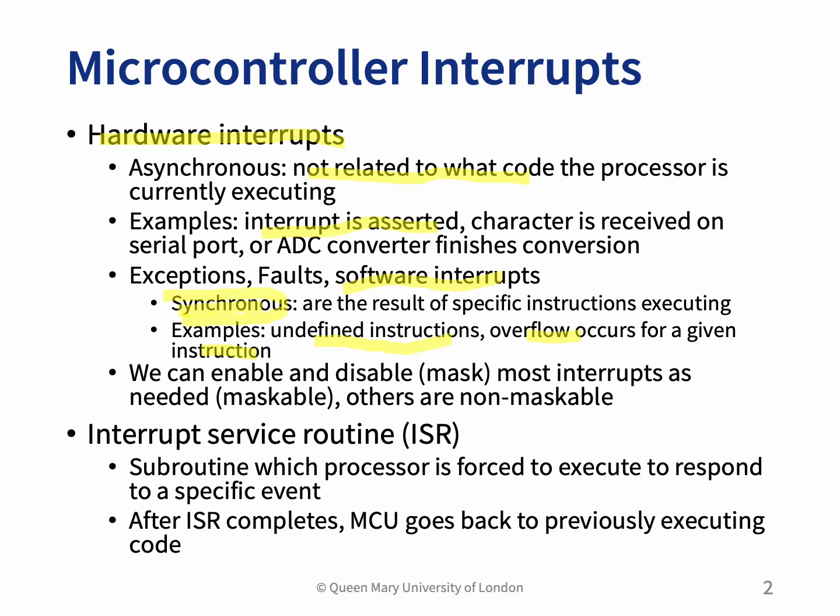We can also enable or disable the mask of most interrupts as needed. It could be maskable or non-maskable. So remember the bit mask operation: it is to clear, change, or remove any unwanted bits as we require. But some are non-maskable, like the watchdog timer, which is non-maskable.